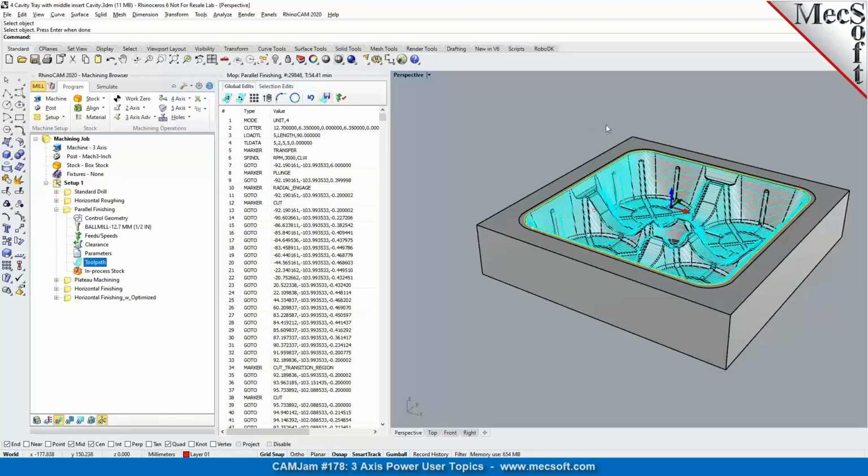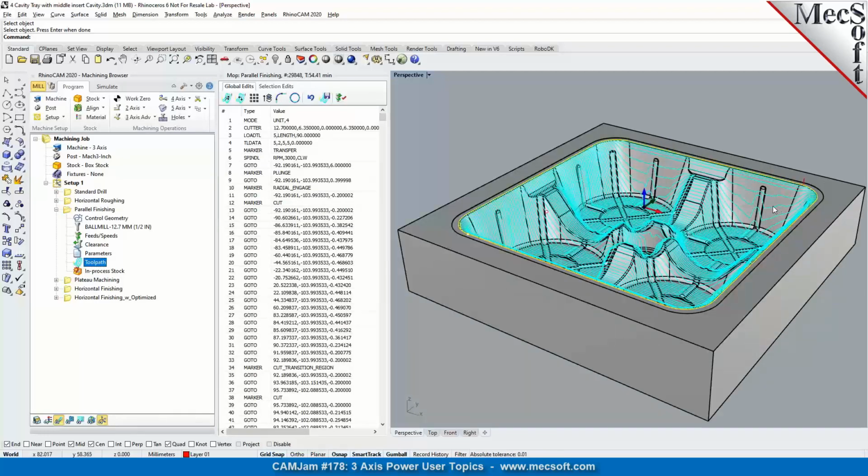Now, one of the many advantages of these toolpath editor tools is, for example, in the case where you had machining, and for some reason the tool broke, or you had a small gouge or something, and you want to cut slightly underneath, or offset the toolpath down in the Z to go back and refinish it without having to modify your part or go back and regenerate the toolpath.